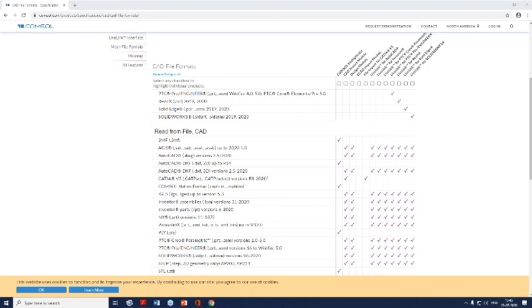And once that is done, rather than creating the 10 turns in the geometry, there are features called coil features available in the ACDC module, through which you can directly provide the number of turns in the physics itself, and you do not have to worry about how to draw that geometry explicitly.